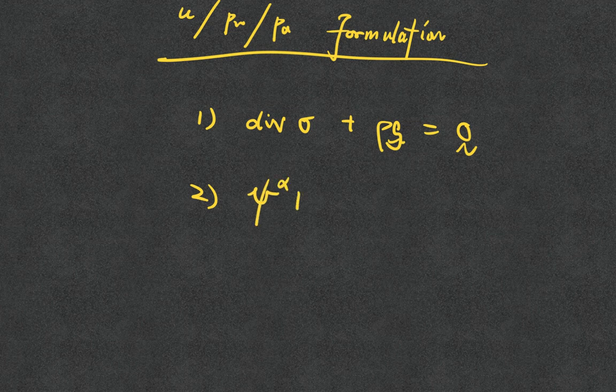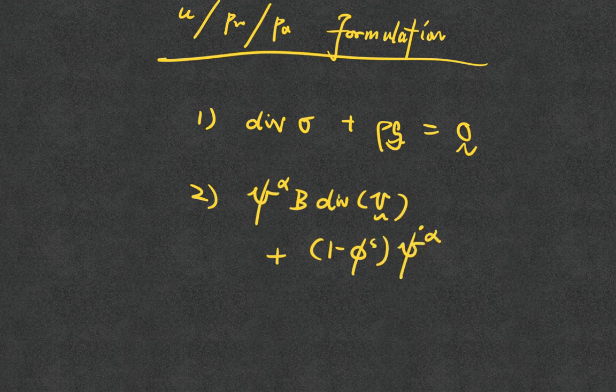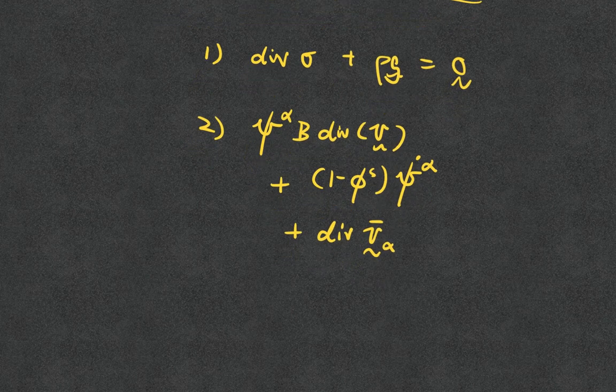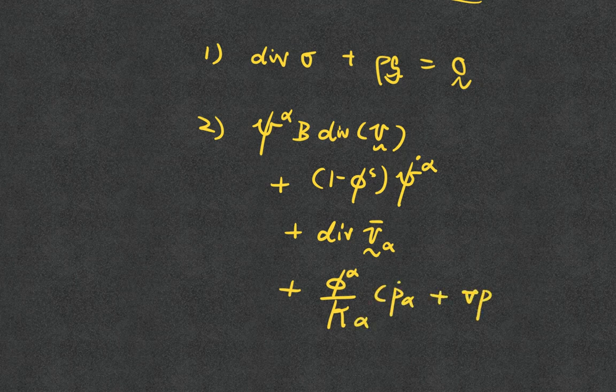And I have the balance term that depends on the degree of saturation, plus the change of the void fractions term, plus the divergence of the Darcy's velocity, sorry, of the relative velocity term times the specific storage term, plus the term that is led by the convections.